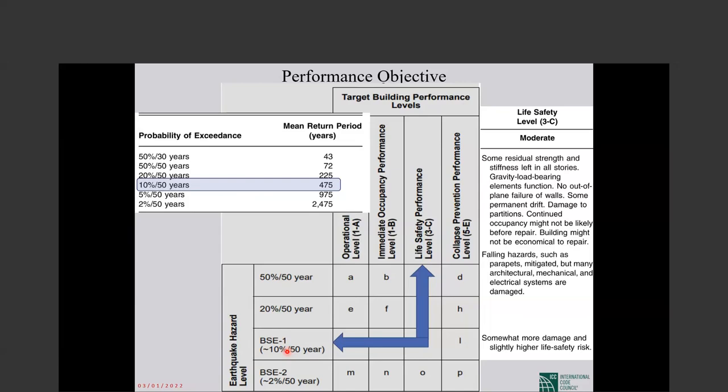There is no R factor in the existing building because the real R factor for an existing building will be very small. So we forget about a factor for R. We go and for every element, find their M factor.